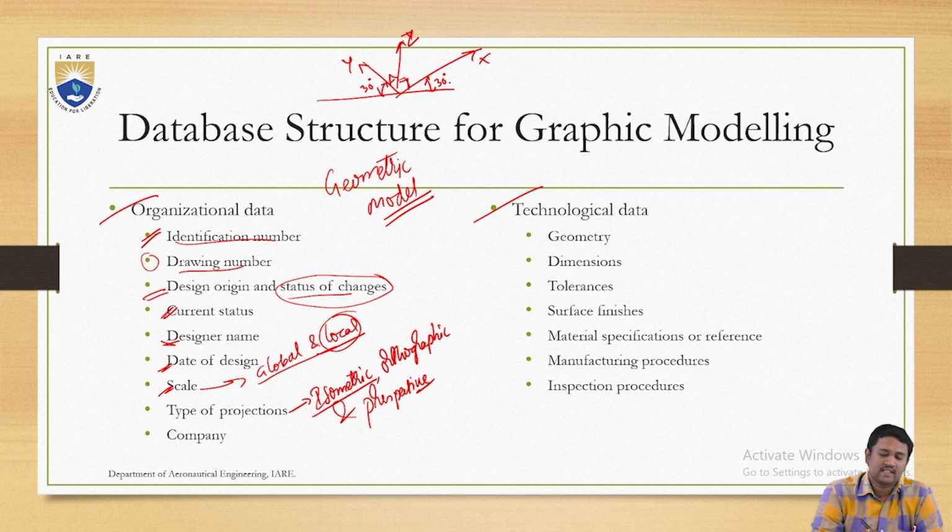This 30-degree inclination adds a small scale factor, that is 0.7 or 0.6, to all the dimensions to get a reduced-scale 3D model, to generate your isometric projection of that particular model.